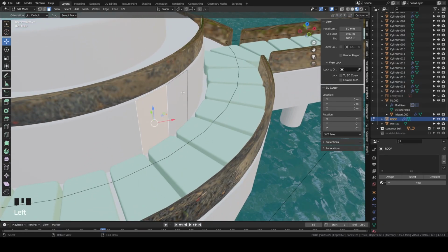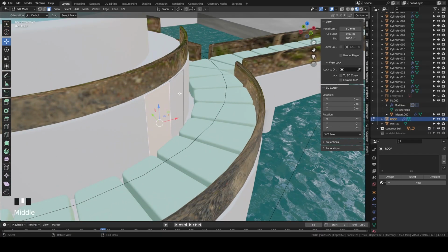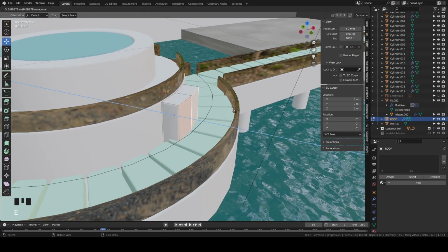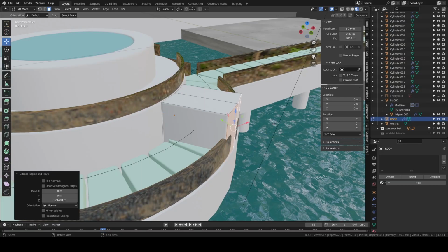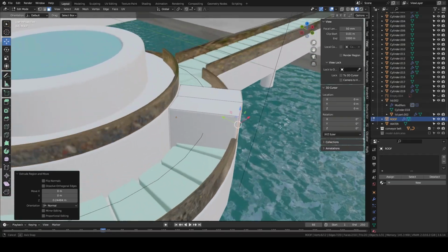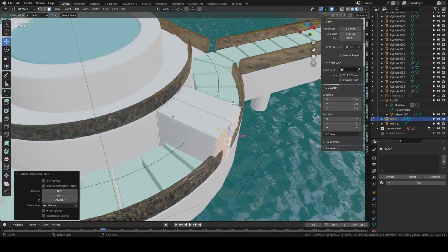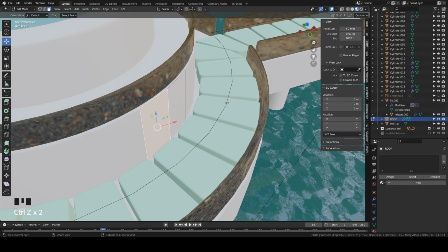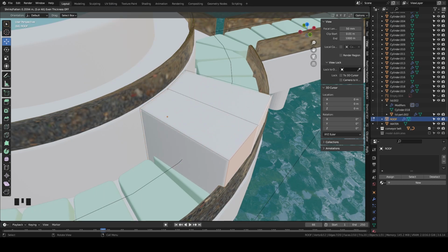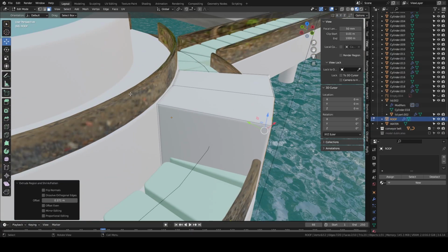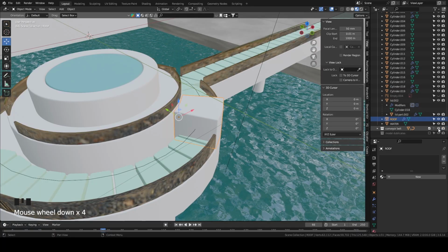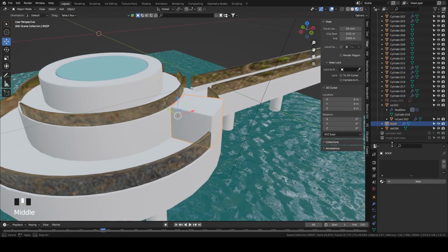And let's see. I'm gonna try this and see if it's working first. So I'm gonna extrude this along the initial axis. You can also go to face, extrude faces along your mouse and drag this out. It's the same thing. Bring this around here. And then I'm gonna hide this thing for now.